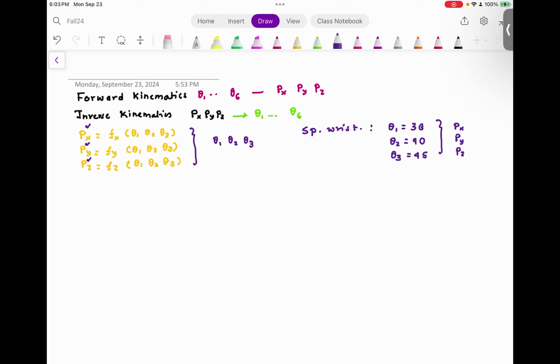You would have a solution when theta 2 is 90 degrees. Now try to run inverse kinematics and you will see the MATLAB solve function will throw an error. And it throws an error because the system becomes singular.